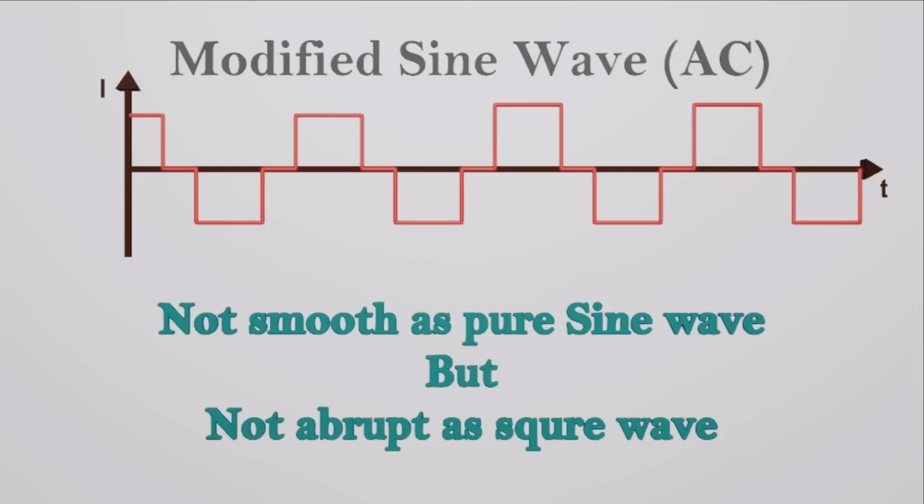In a modified square wave design as shown above, the square waveform shape basically remains the same, but the size of each section of the waveform is appropriately dimensioned so that its average value matches closely to an AC waveform's average value. As you can see, there's a proportionate amount of gap or null areas between each square block. These gaps ultimately help to shape these square waves into a sine wave-like output.